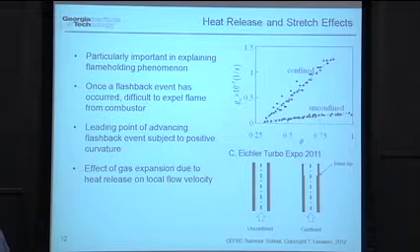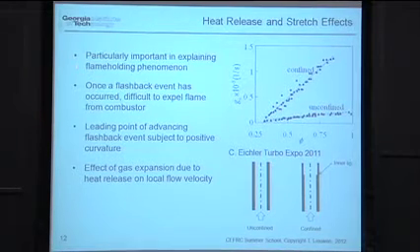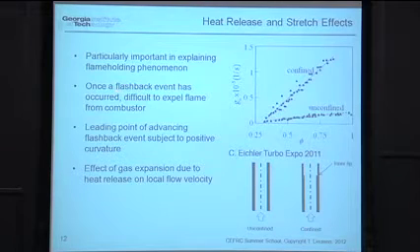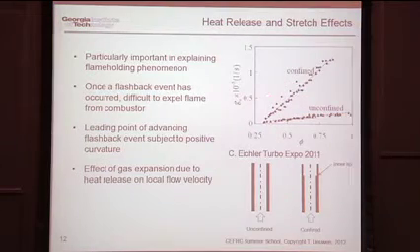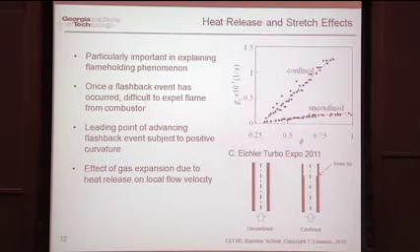All right? And so what this points out, like I said, is particularly important in understanding this distinction between flame holding and flashback. Once a flashback event has occurred, it's really difficult to expel the flame from the combustor. In other words, if you design the system and say, oh, a critical flashback gradient of 0.5, that's everywhere greater than this result, I should be fine. You can see once the flame is confined, that's not good enough. The flame will stay there once it's stabilized.